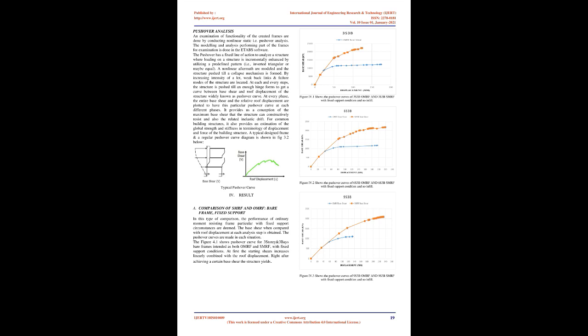Determined by the foundations resting on medium soils, the displacement boundary conditions in the bottom part of foundations may be looked at as hinged or may be fixed. As the modeling of soils isn't in the range of the research, two boundary conditions, fixed and hinged, which symbolize two extreme conditions, are considered.